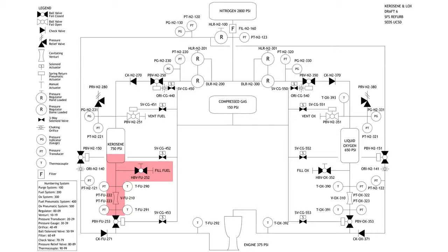And so during the fill procedure, our whole system's hooked up, for example, on the I-beam, and if you don't know what an I-beam is, don't worry about it right now. We'll fill the kerosene side. We literally have a kerosene fuel tank. We fill it with kerosene, we close it up, we pressurize it to 30 psi, and we open a manual ball valve on that. Fluids flow from our little manual tank into our system. And based on a pre-measured amount, we know how much kerosene we have inside the system. Kerosene doesn't vaporize. We don't have to worry about it boiling off or anything like that.